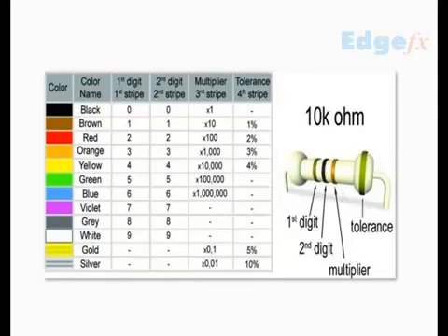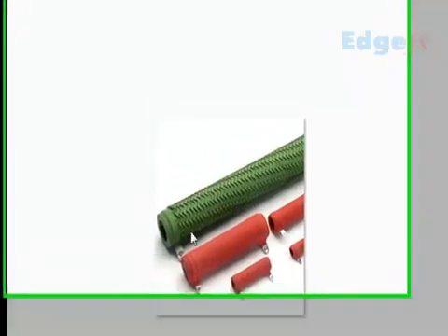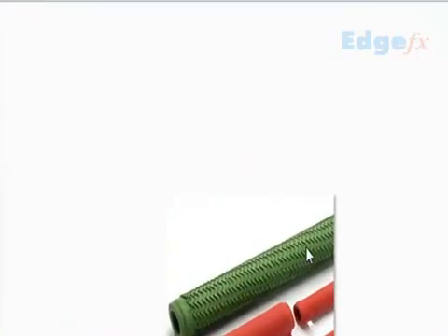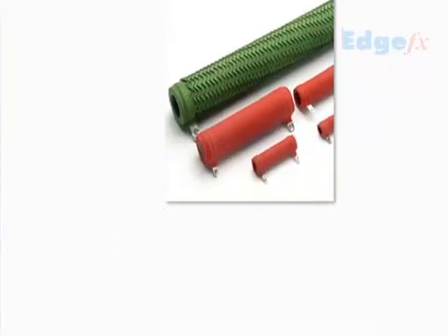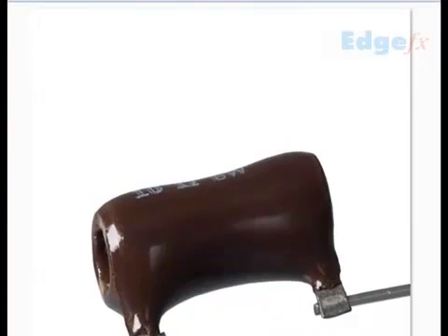But when you look into certain higher wattage resistors, these are called higher wattage resistors, where they are typically wire wound resistors, and the value of that resistor is written in terms of its ohms and the wattage. So these are called high wattage resistors, and high wattage resistors are typically used in industrial applications. This is also another high wattage resistor. They are all wire wound resistors, and the value is written here. So there is no difficulty in finding out the value of this particular resistor.